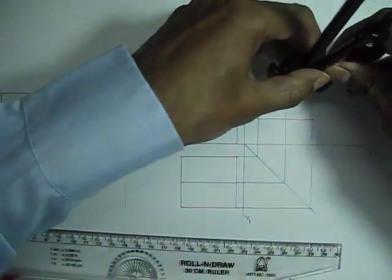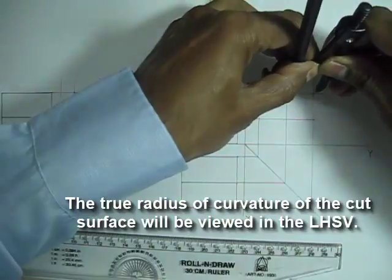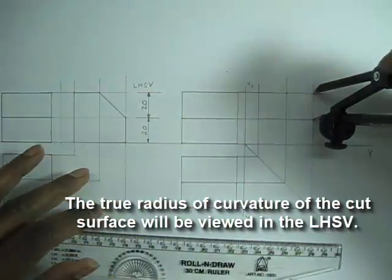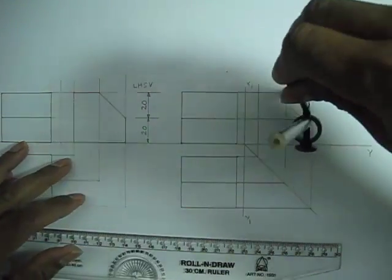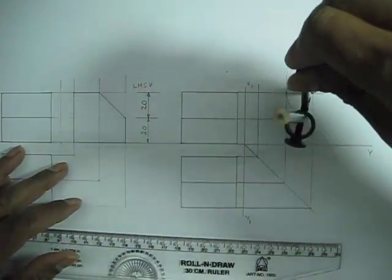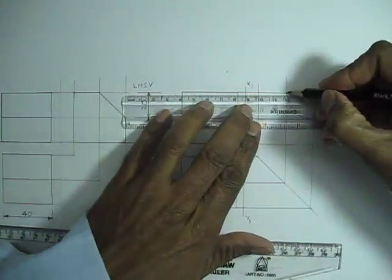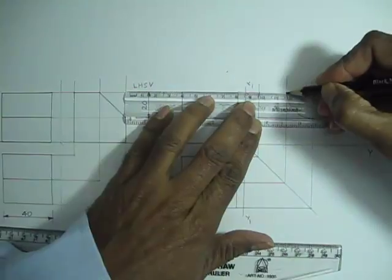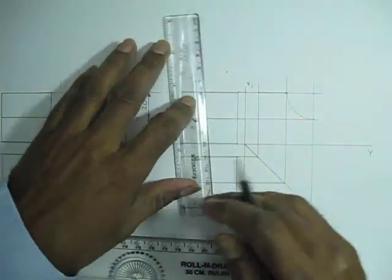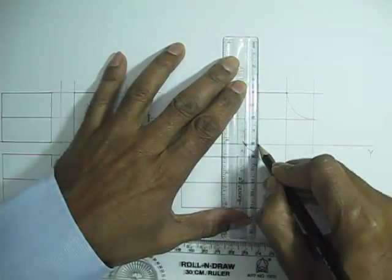Using these corners we will draw an arc of 20 mm radius, because the curved surface will be visible in the left hand side view in its true dimension. This arc of 20 mm radius basically represents the curved surface. So in the left hand side view we are able to see the curvature of the curved surface. Now we can complete the rest of the left hand side view.